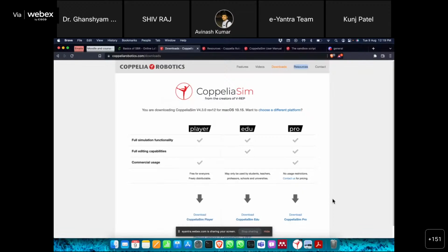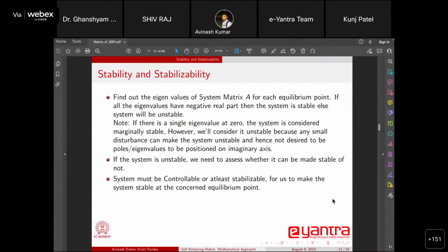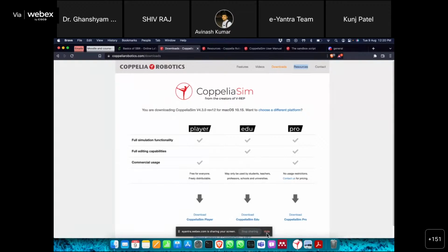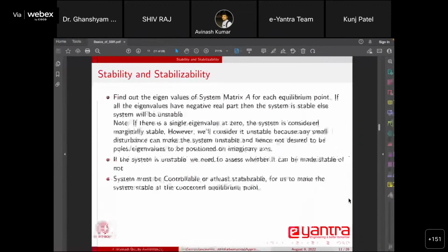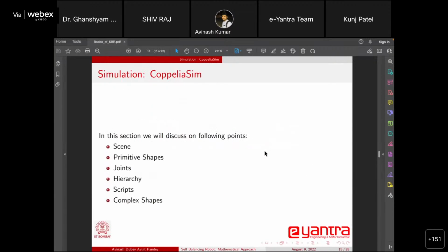Once you have the model, with the LQR control technique, the tuning is very easy. You add certain weights, feed those weights into your system model, and immediately you get a new gain matrix K, and you can then stabilize the system. So tuning becomes very easy with LQR, because your model takes care of the system. In PID, this becomes very difficult because you don't know the system. As soon as you change certain parameters of your system, you have to retune your PID control.